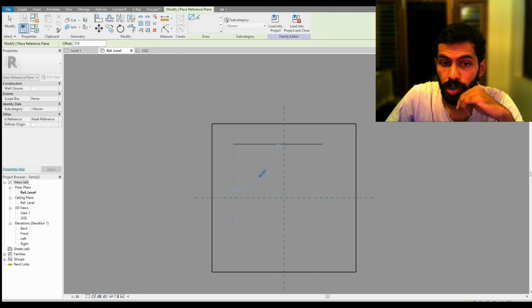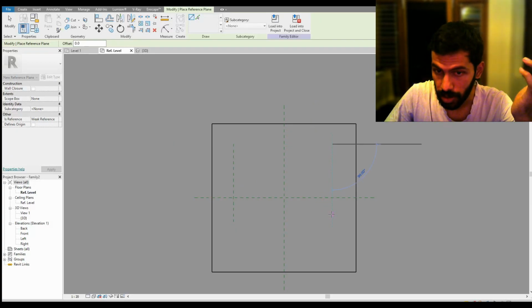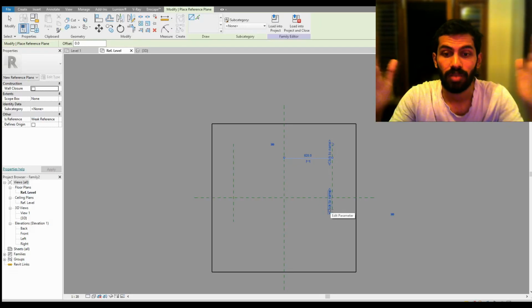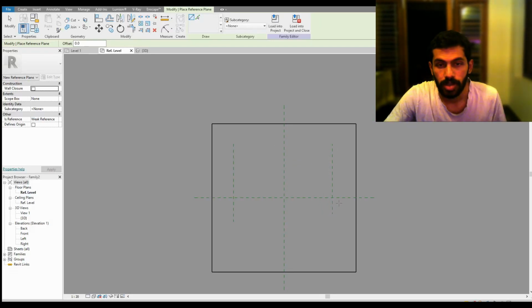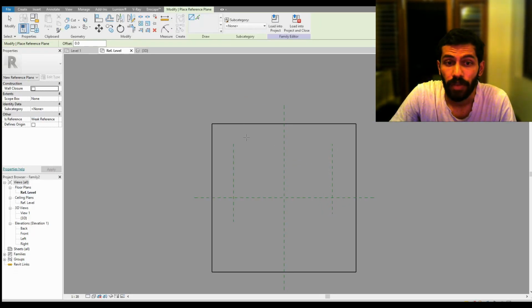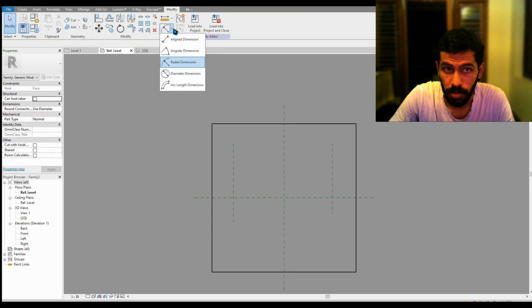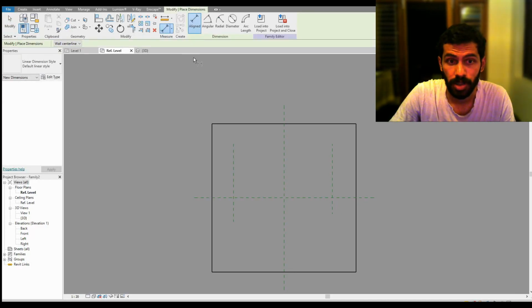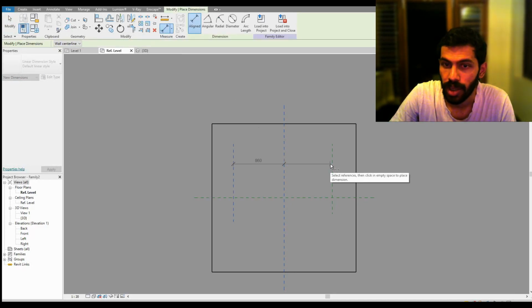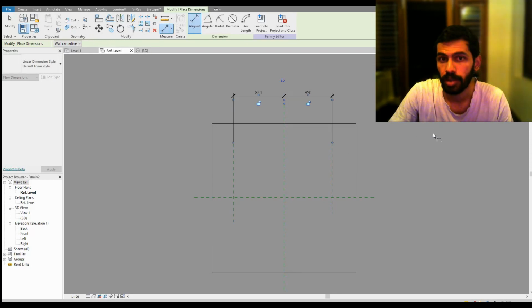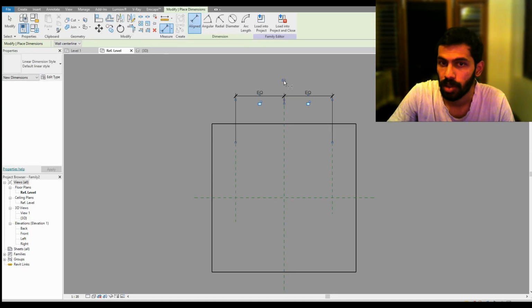If you're changing the width, I would like to have two planes vertically so that it can change the width from there. The second point is, if you have two or more reference planes, I like to make use of an equality constraint. So get into Aligned Dimension, pick the first plane, center plane, and the last plane, click outside, and enable the equality option.